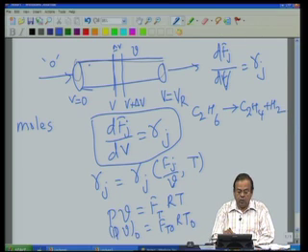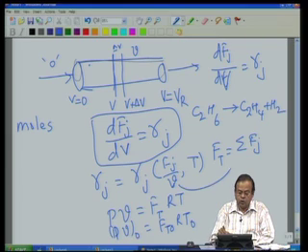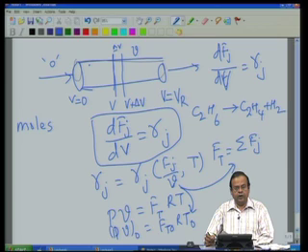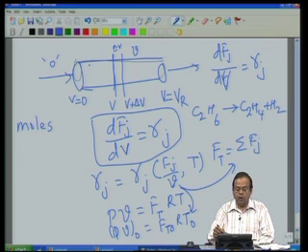And this now has flow rate Ft, and flow rate Ft is nothing but the summation of Fj. So, the molar flow rate Fj not only appears as Fj, but also in the volumetric flow rate. So, all this will have to be considered together if we have a reaction in which there is a change in number of moles.